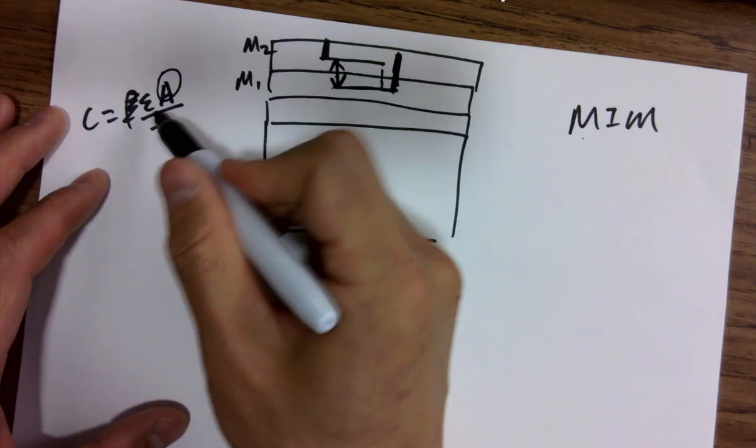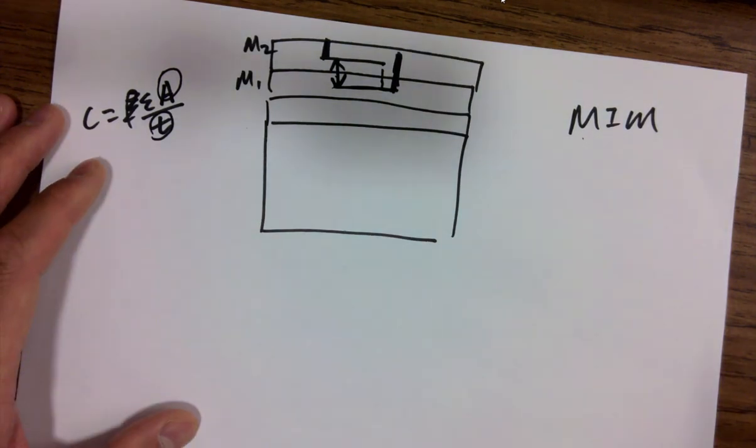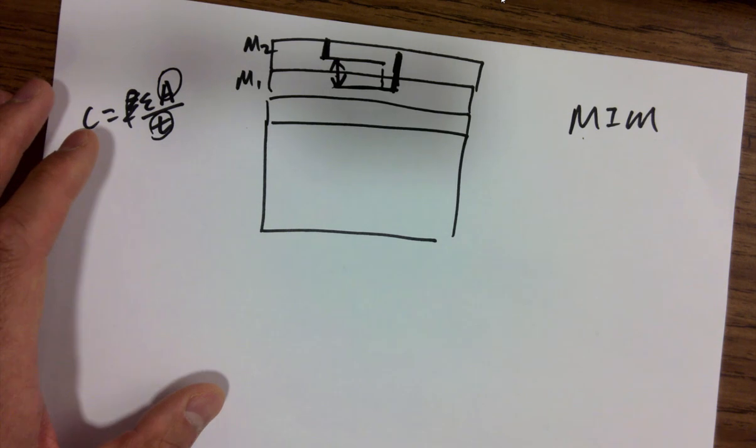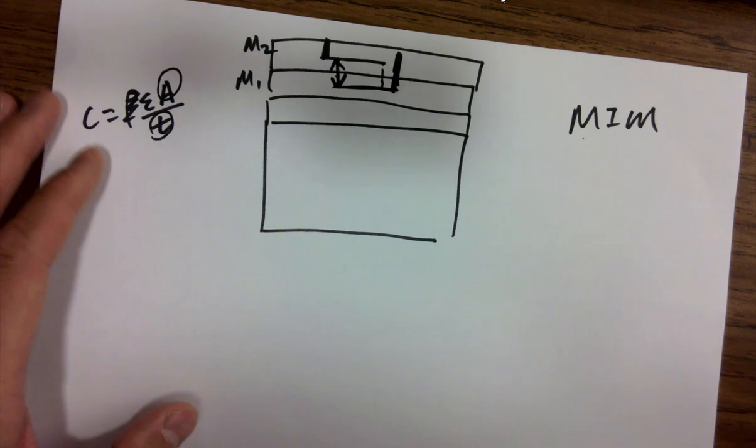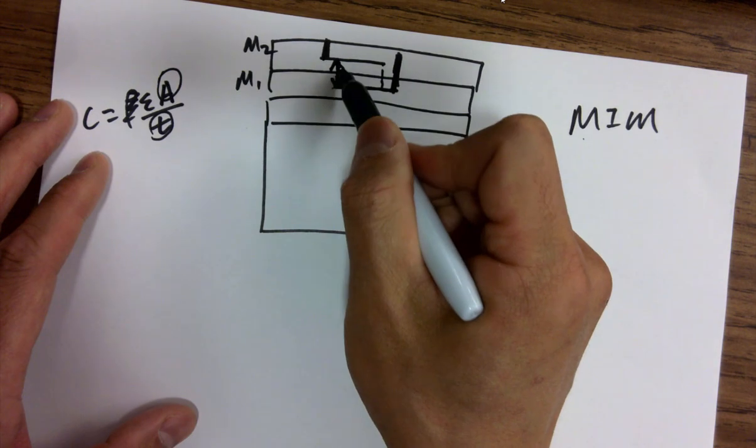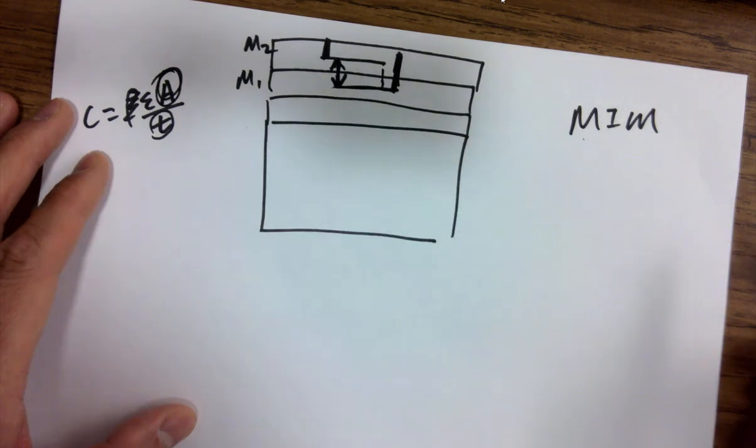Shorter distance is also larger capacitance. You could change the length, maybe the thickness, but there's no way to change the thickness, because the thickness of the insulator is defined by the process, right? So you can just change the area.